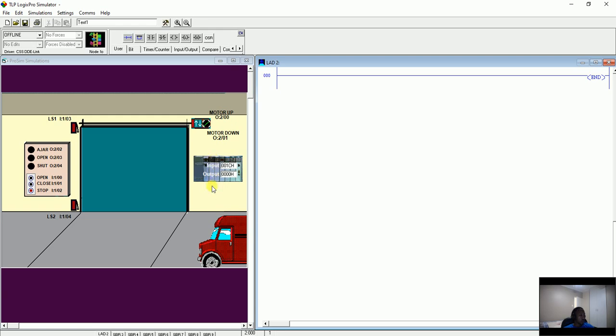Then on slot 1 we normally put a communication module like an Ethernet module or Profinet or any kind of communication module. Then from slot 2 we normally put our I/O modules, talking about analog in, out, digital in, out. But on that one I'm going to specifically make a video.